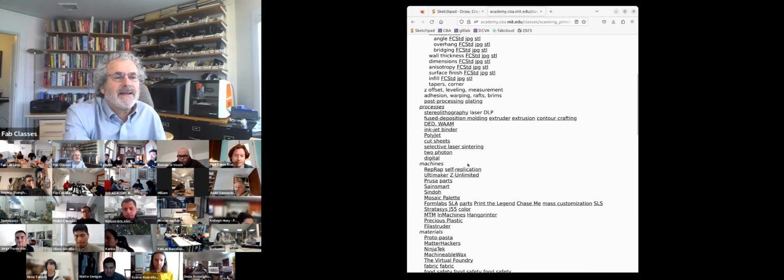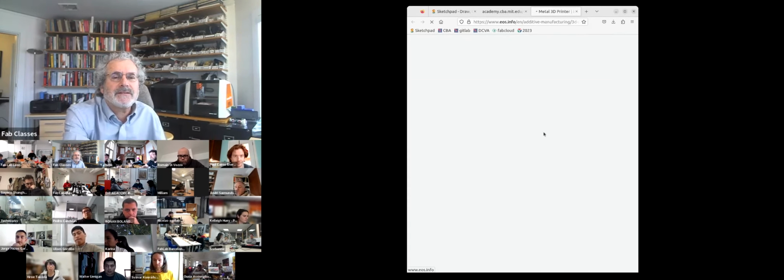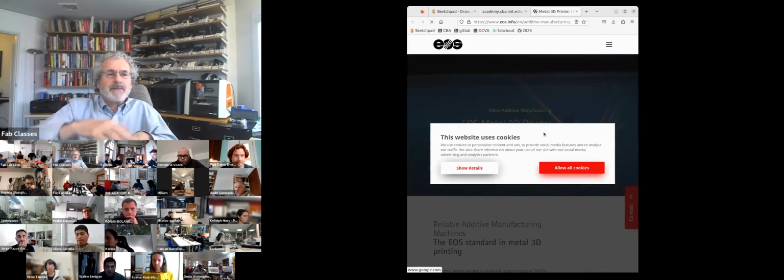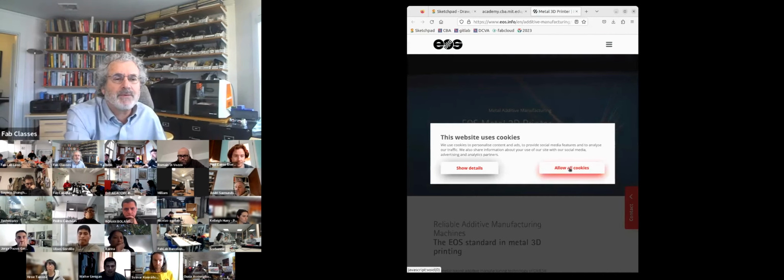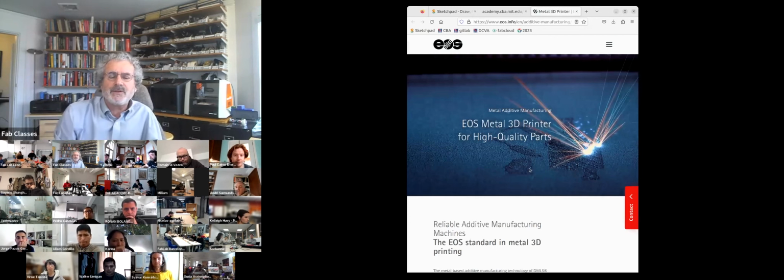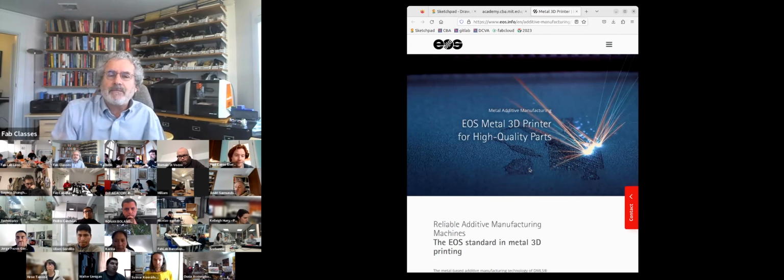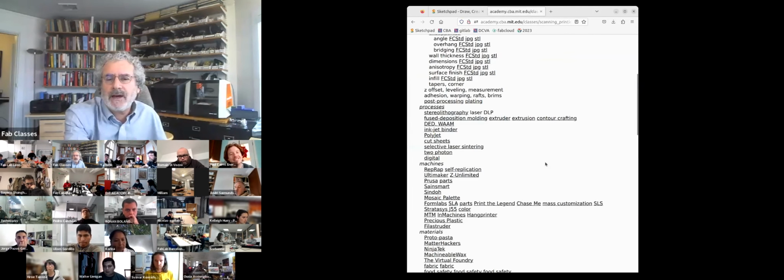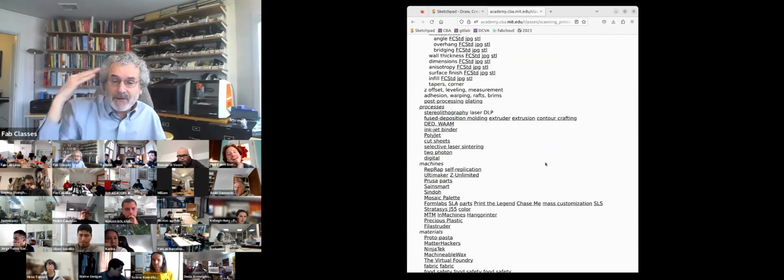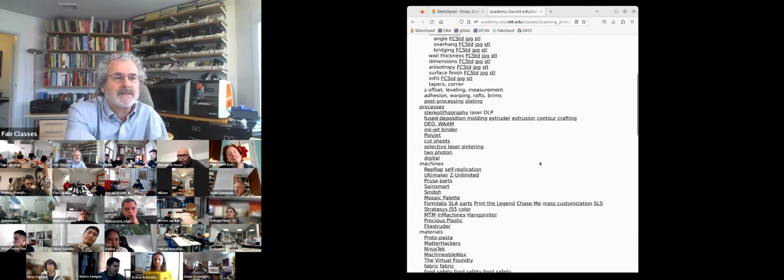So I'll drop that. Then laser sintering is where you spread layers of powder, but rather than printing, you use a laser to fuse it together. And so this is used in the highest end metal printers, and these cost $1 million. But it's also becoming accessible in laser fusion printers that are not millions and not thousands, but tens of thousands that I'll talk about.